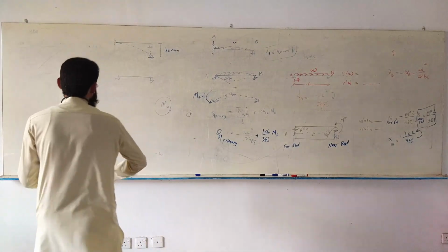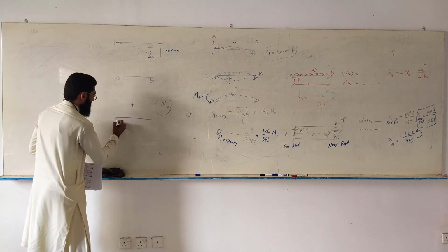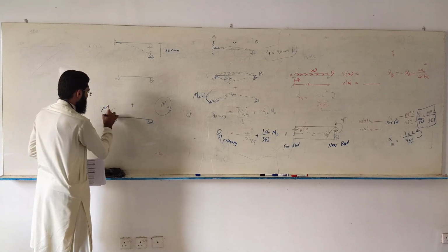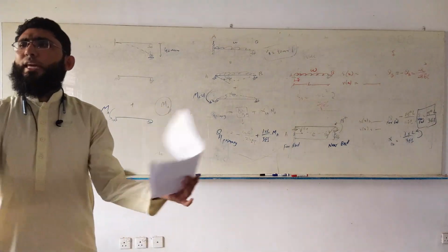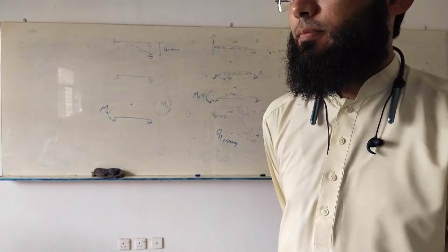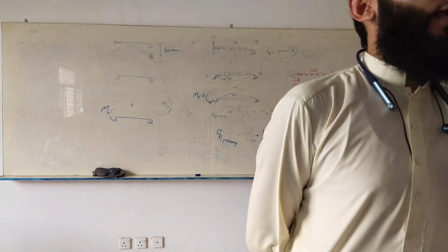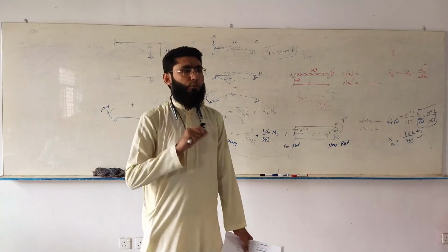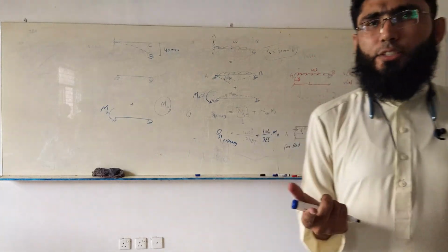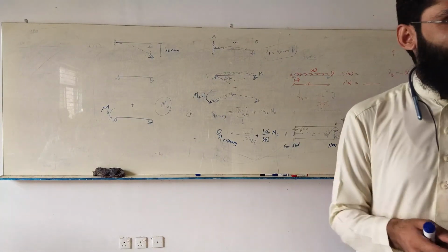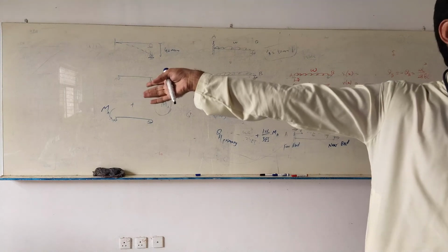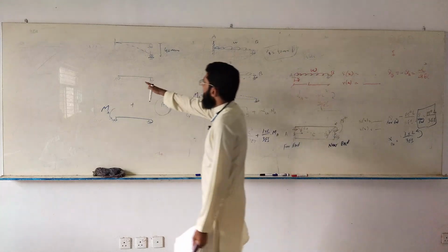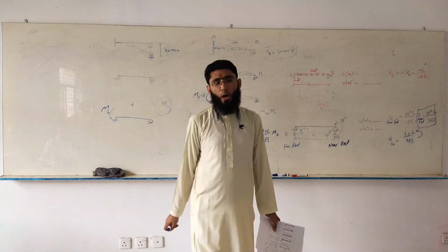Only then you can have another structure like this. If MA is not even part of your equation, how can you find it? And the only way you can have MA in your equation is to treat the rotation at A as your displacement measure. Now that is 0. That's the problem. The rotation at A in the given beam is 0. It is fixed. And there is nothing happening at A. There is only a problem at the other end. So how do you solve it?